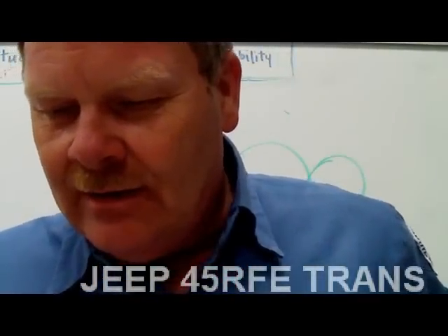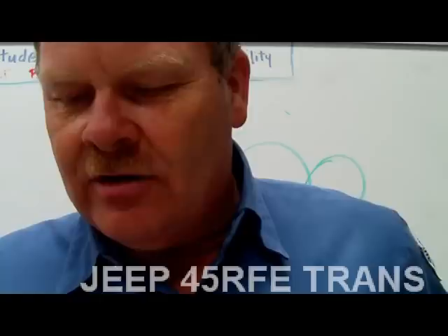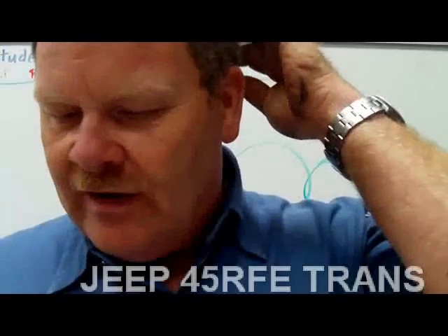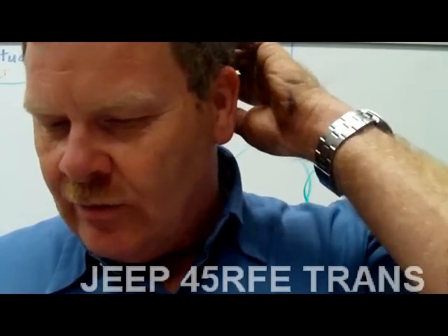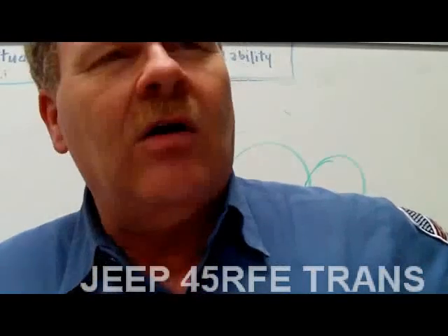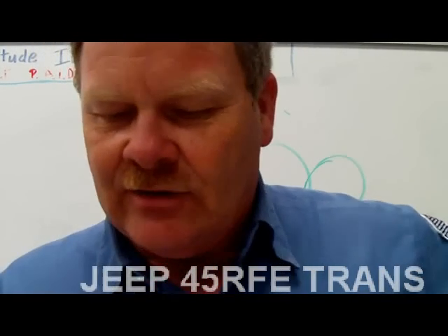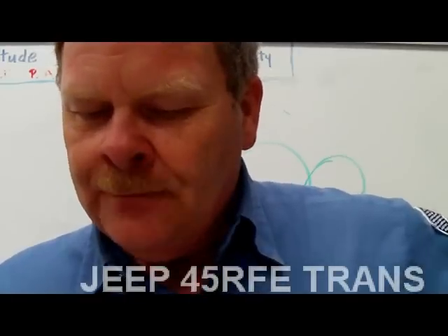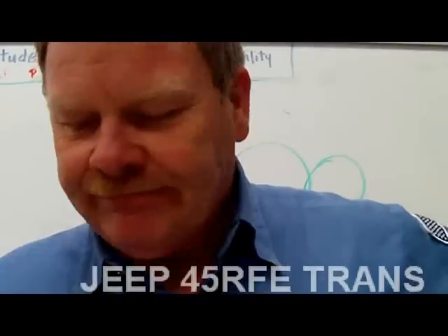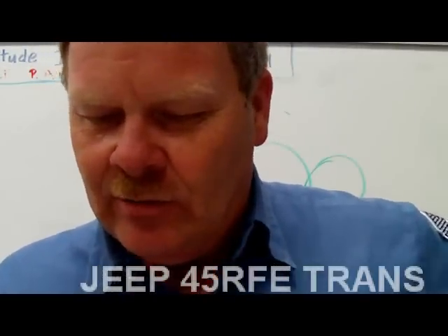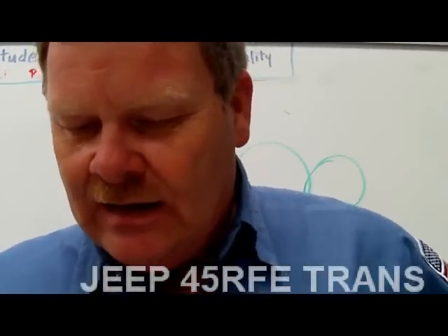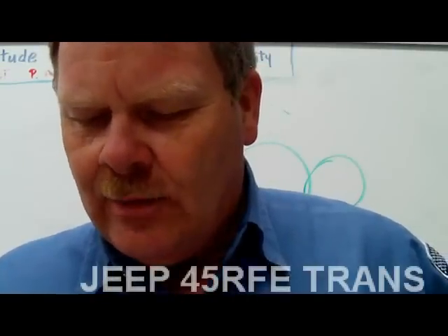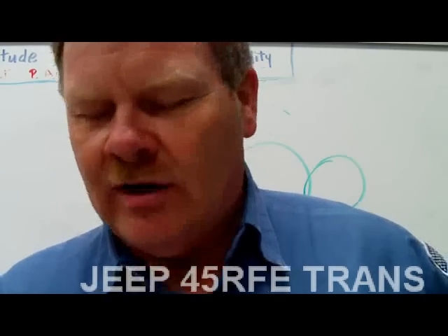Anyway, the manual valve has 4 positions: park, neutral, reverse, drive, and 2 low, in the RFE. And it holds the low reverse switch valve. The valve body also has a low reverse switch valve, and that separates the circuits for reverse and all other manual valve positions. This stuff may sound like Greek a lot of the time if I'm going this fast, but don't worry, it's all in the book. The valve body contains a solenoid switch valve. We're getting up close and personal with one particular transmission is what we're doing. That routes fluid to either the low reverse clutch or the torque converter clutch control port. And there's the park, neutral, low, low reverse solenoid.